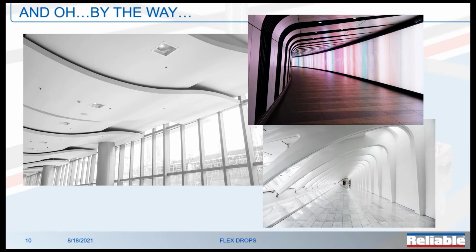So now instead of a drop coming straight down and trying to hit that little 4-foot lateral increment, I've now got to somehow swing that fire sprinkler so that it's parallel to that particular linear panel. So how do we address this, right? With fittings and extra labor. And that's where that cost comes in. And then, of course, what comes along with additional fittings is the potential, anyway, for additional leaks. And then we see things like this. Now we're going to take these weird shapes and we're going to hang them below the ceiling.